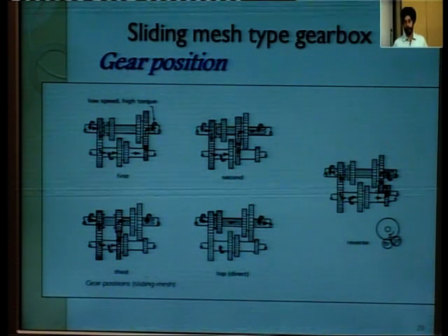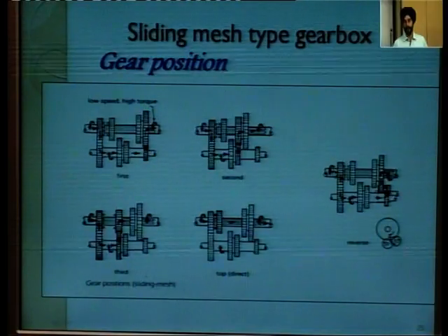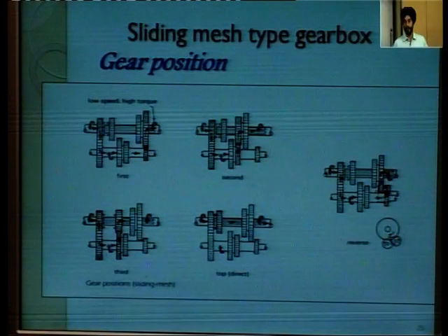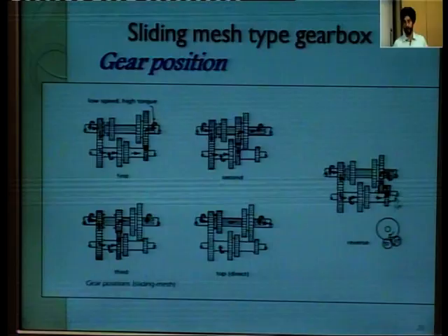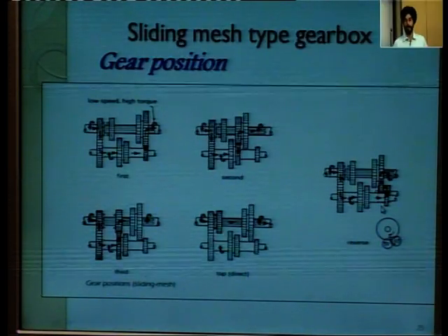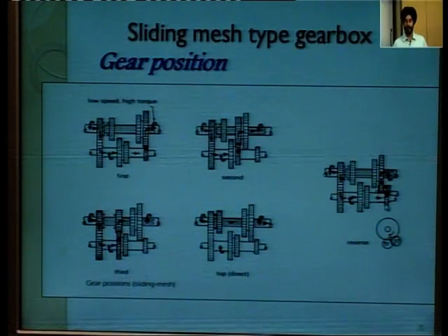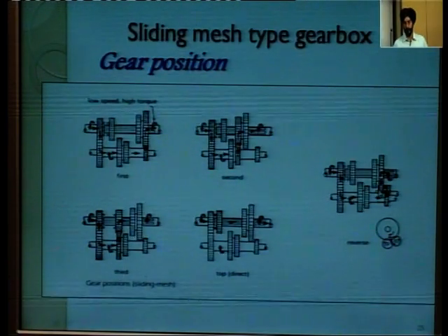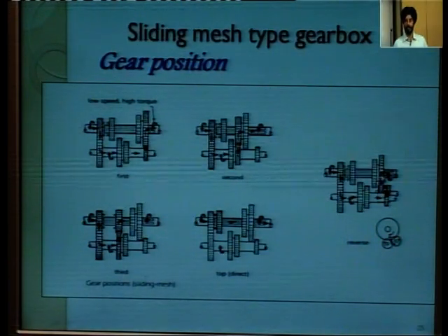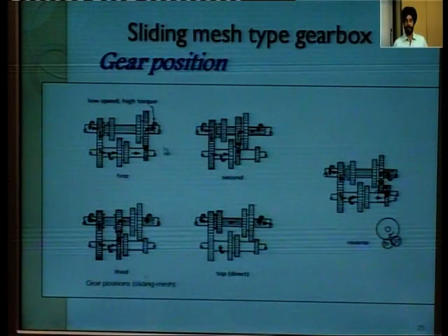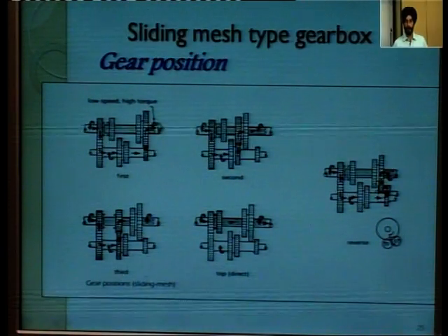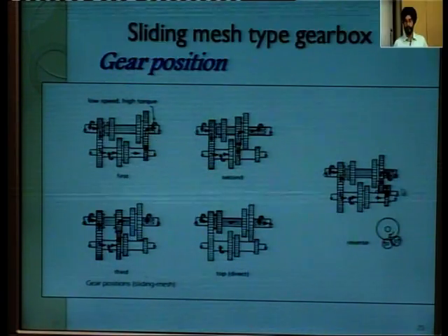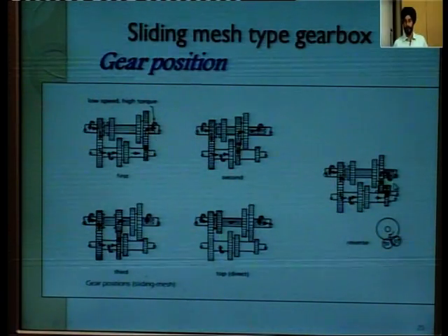So, when we want to place a reverse gear, this mechanism shows the reverse gear, in which an idler gear is there. First power comes to the smaller gear, then it goes to the idler gear, then idler to reverse gear. In this case, the direction of motion from first gear to reverse gear is opposite.